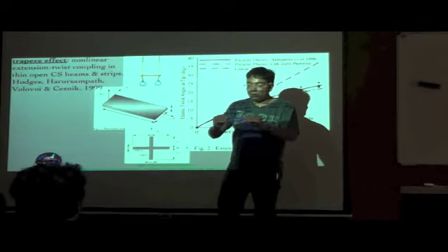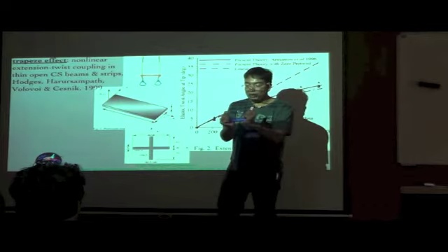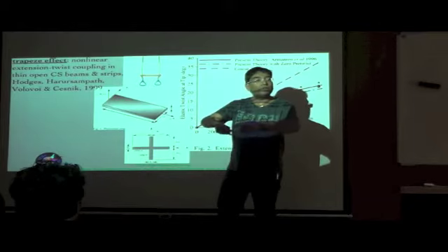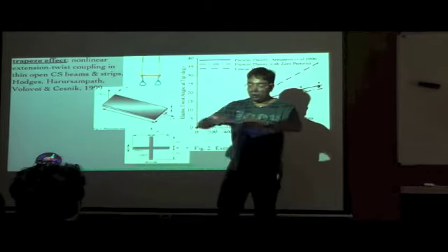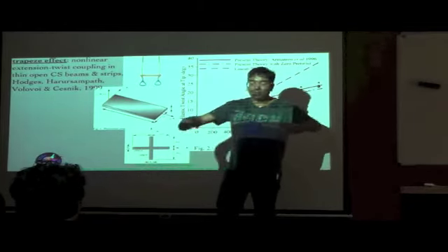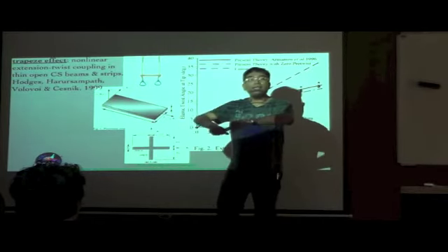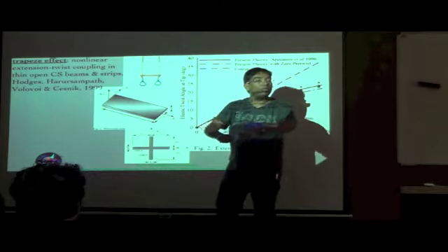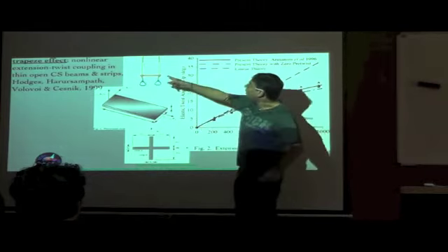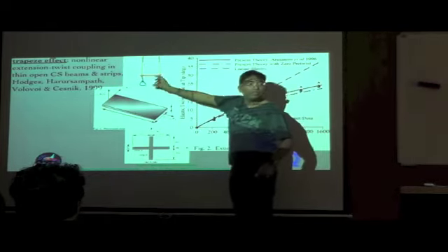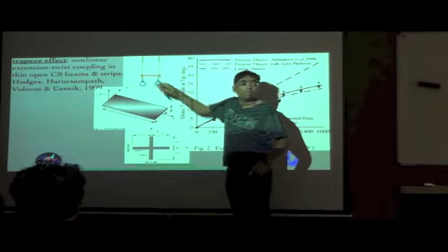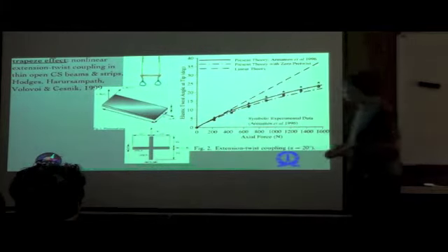If the fibers were left as they are, it is much easier to twist it. But once you apply a tensile load and give those fibers a pre-tension, it becomes more difficult to twist. The same thing can be very easily observed through very simple experiments performed on this particular apparatus as well.